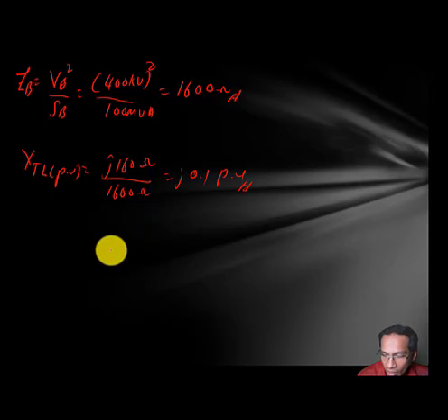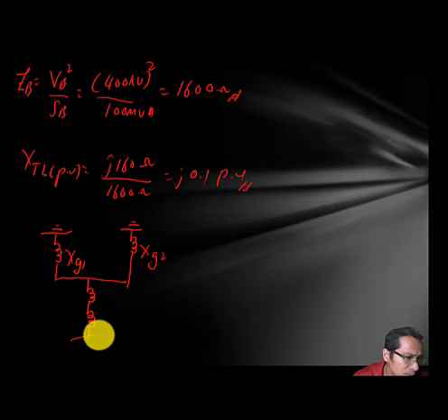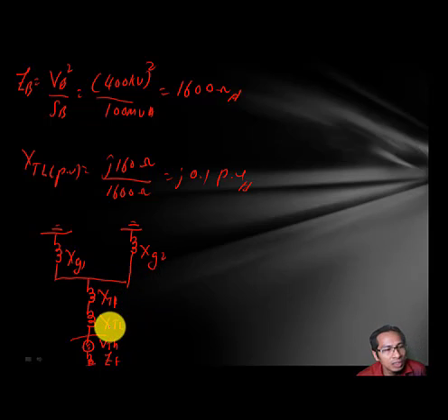So from the circuit, to calculate the fault current, we use Thevenin theorem. Okay. So we short all the sources. This is generator. We short all the generators. So we just use XG1. And then we short another generator, generator 2. So this XG2. And then we have transformer, and then we have transmission line. Okay. This is bus bar. And then we add Thevenin voltage over here, and then over here we have fault impedance. Okay, fault impedance. So we have VTH, this is Z fault. This one XTL, this one XT1. Okay, so this is our circuit.